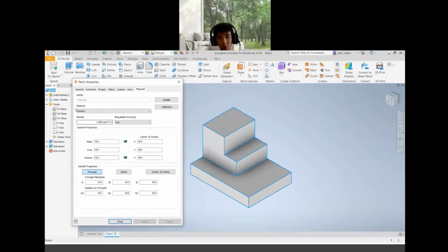Okay, you will see, I will show you. I would like to have this particular feature here. The secondary feature will be this one. So you have to ensure you select the correct surface to become your work plane. In Inventor, after I sketch it, this is the correct one. It should look like this. So I just rotate my view here.